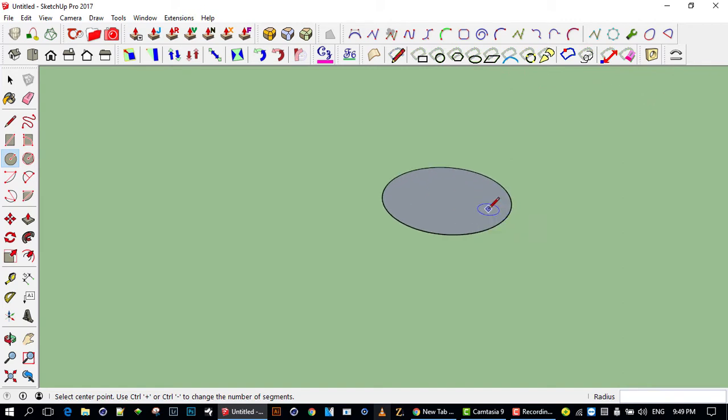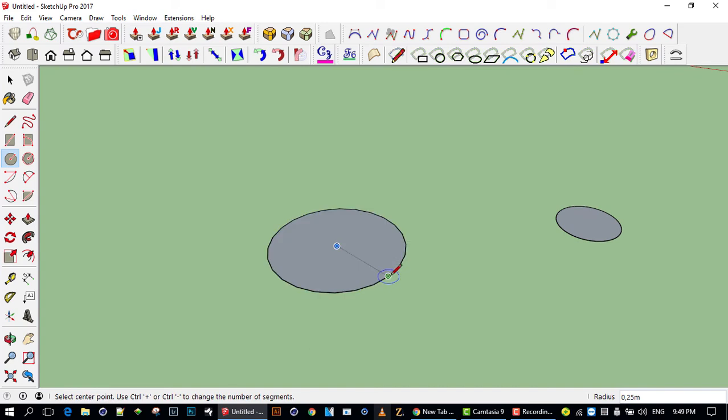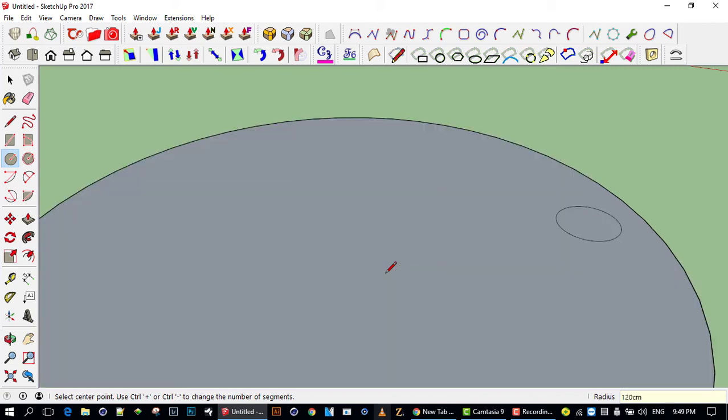It gives me a 12 centimeter radius there. So remember there are two indications. I'll do it again. I must click off here, just so we can get back to the original 24 segments. So the first one, I drag and I'll go, okay, let's say 50S for segments, which smooths it nicely, and then I say 20 centimeters, enter.